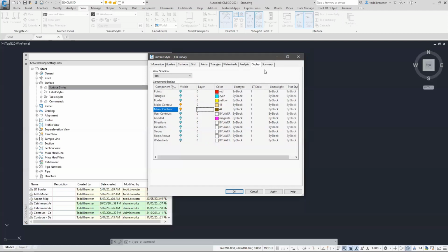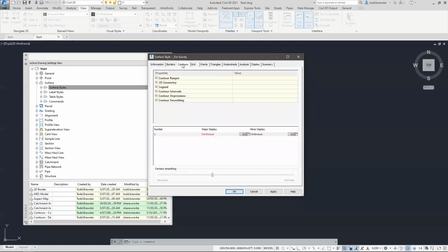All right. So I'm showing contours, so I need to control the contours in my drawing. So that's what the contour tab's for. So for contours, I'm going to set them as an interval of 0.2. So I want my majors at 1, which remember the relationship, so I flipped it up. And I'm an engineer, not a surveyor, so I'm more than happy to apply some smoothing. And you can flip the smoothing mode into one or the other. If it's on add vertices, you can use this tracker across the bottom to increase and decrease the amount of smoothing. All right, let's make our style.